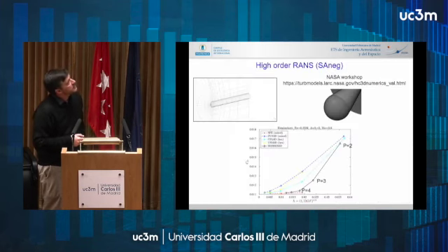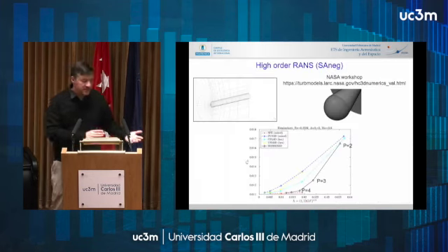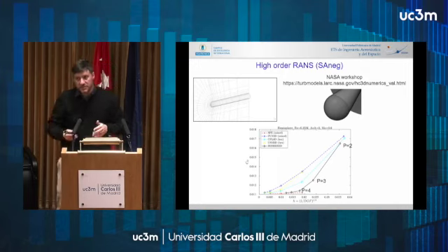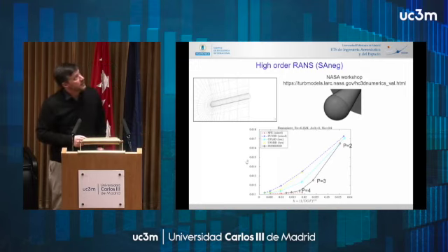Okay, so in turbulent flows, you can run RANS simulations, you can run LES simulations, and in our solver, we can do both. Here I'm showing you a RANS simulation with the Spalart-Allmaras model for this particular NASA workshop body. And what we observe in this RANS simulation is that we get a very highly accurate solution when we increase the polynomial order. So this is our solution, HORSES3D, from P2 to P6, right?